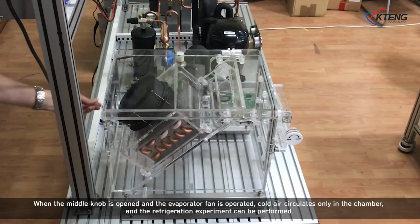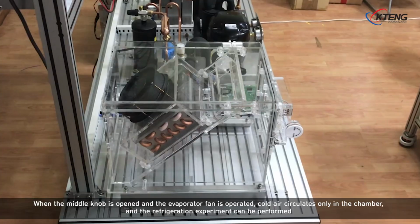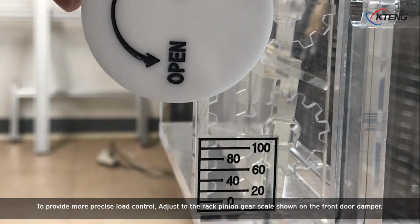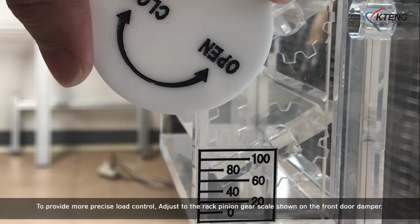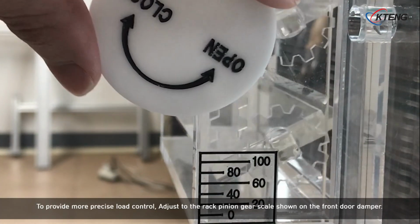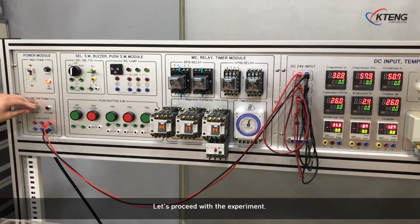When the middle knob is opened and the evaporator fan is operated, cold air circulates only in the chamber, and the refrigeration experiment can be performed. To provide more precise load control, adjust to the rack pinion gear scale shown on the front door damper. Let's proceed with the experiment.